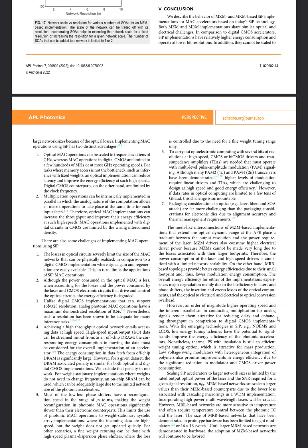Limitations of the silicon photonic multiply accumulate operations: accounting for the losses and power consumed by the laser and circuits that drive and control the optical circuits, the energy efficiency is degraded. Analog multiply and accumulate operations have a maximum demonstrated resolution of 8.5 bits, and this is accurate for many inference tasks today.